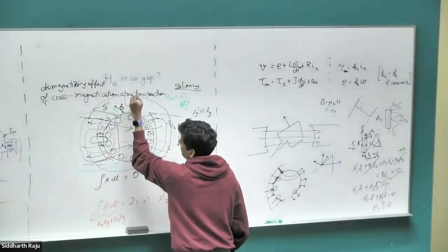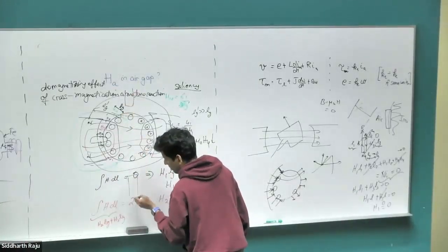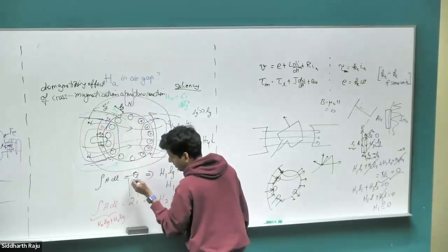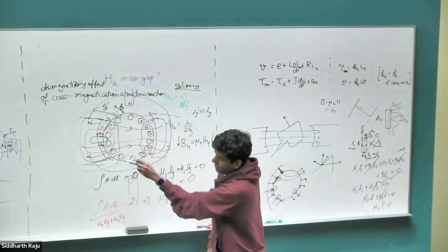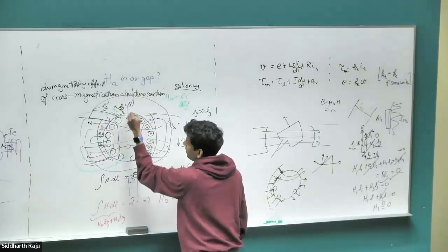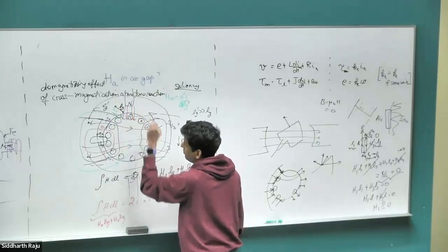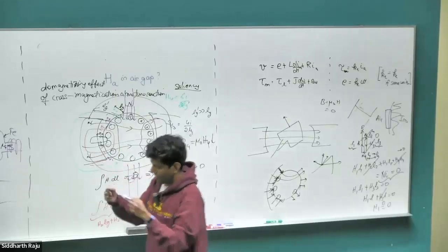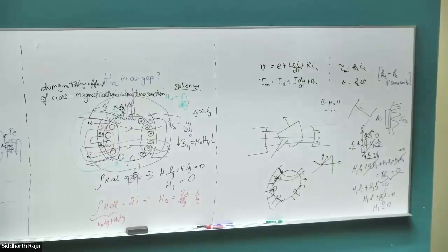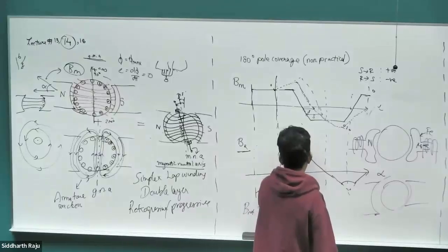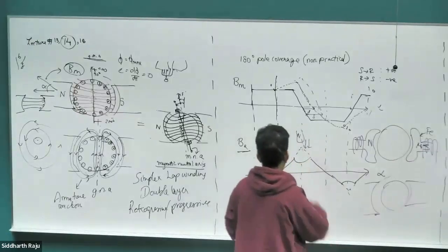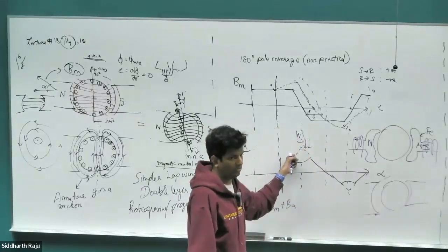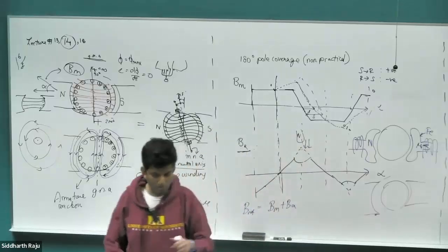Let's say I put a magnet here and a magnet here. North and south here. Right? So the B field spiked at that point. Now basically I create a magnetic field in the opposite direction so that I get the same effect as suppressing the peak that I have there. Right? So if I had a magnet here which is creating a magnetic field that's in the opposite direction, that would effectively just suppress the peak that I saw there. So those are called interpoles, and we won't use a magnet per se.